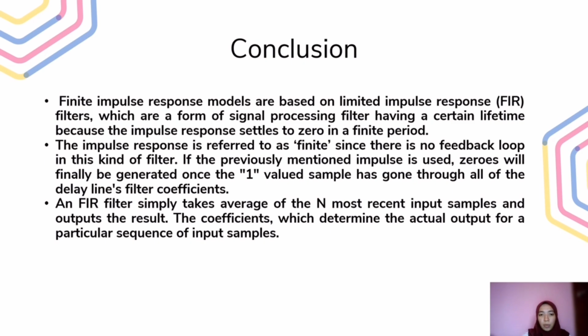The impulse response is referred to as finite since there is no feedback loop in this kind of filter. If the previously mentioned impulse is used, zeros will finally be generated once the one value sample has gone through all of the delay lines and filter coefficients.